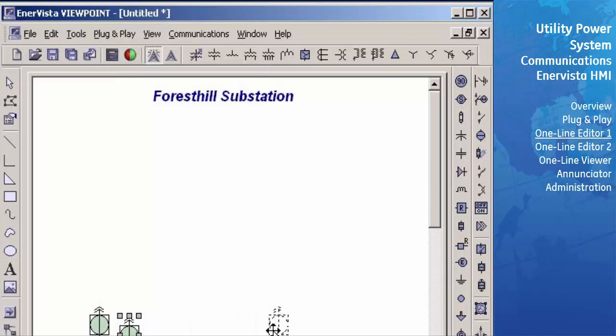You may now move this new copy of a device to another part of the schema. You can also copy and move devices by holding the Control key and then dragging the copy of the device to another place. If you also press the Shift key while dragging, the copied device can be moved on the same horizontal or vertical axis.